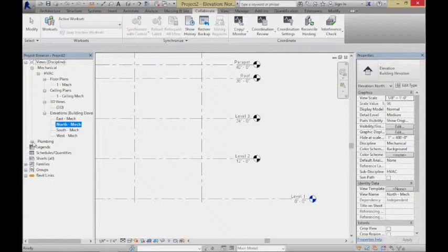It's really either way that sort of makes sense for you, but if I'm going to put them at level 2, I'm probably going to go to level 2 and put a ceiling plan. Okay, so how do I do that? You will notice that over here right now in the ceiling plans and the floor plans, I only got level 1. That's because I took out some levels and recreated some new ones. I need to create some new ceiling plans for myself. Not to worry, I can.